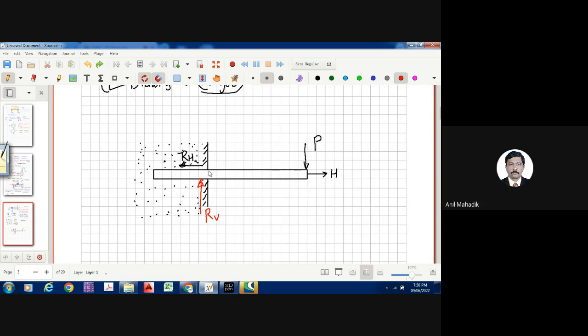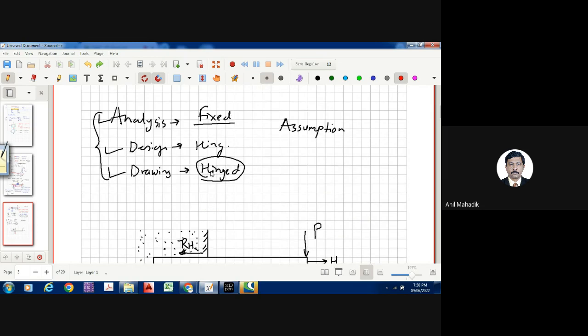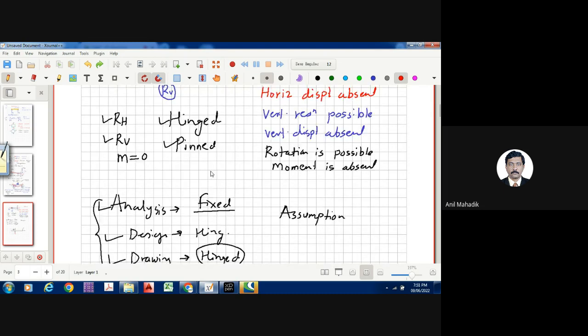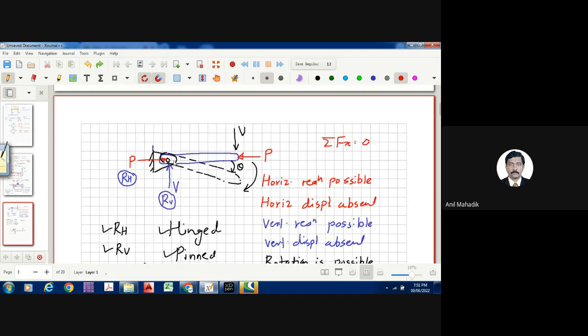Yes, because now please keep in mind we are talking of the supports. That's why I told you here, look at the support, don't look at somewhere outside. See, this rotation I'm showing is here, but actually here also you can see there is a rotation in this direction. So previously this line was here, this blue line, and now there is this inclined line. So at the support, there is a theta here. Please keep in mind. Don't look at this. Let me remove this itself. Don't look at this theta here. See this here. Okay, it's very important because at this point it is rotating.